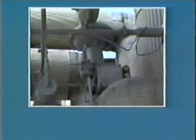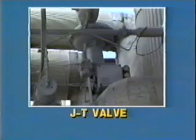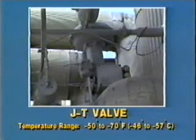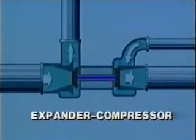In pressure reduction, a pressure-reducing valve called a JT valve reduces the pressure of the gas stream. The reduction in pressure causes a reduction in temperature in the range of minus 50 degrees to minus 70 degrees Fahrenheit.